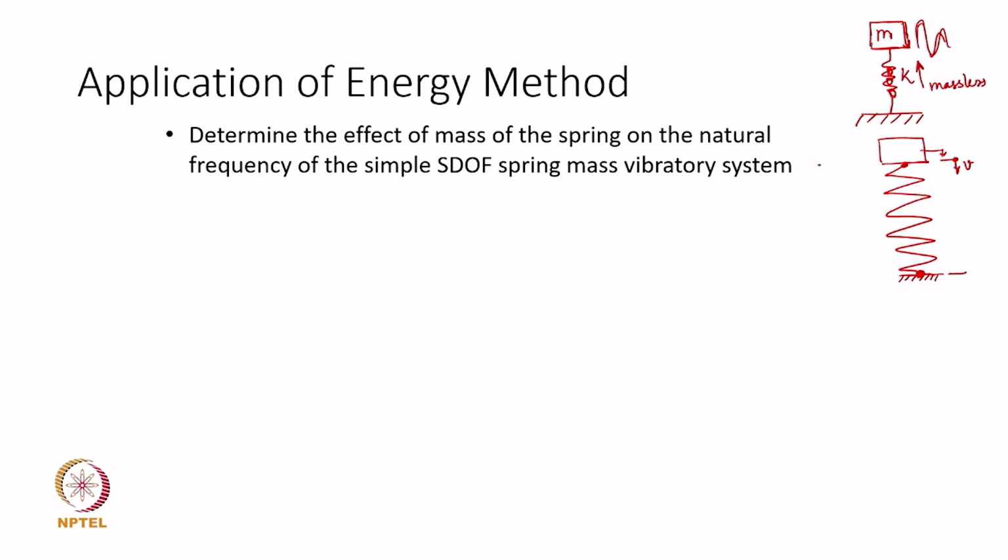Similarly, if I show the displacement, then the displacement is going to be maximum at this end of the spring, and it will be 0 here. So, we can assume a linear displacement profile, which means that if the displacement here is 1 unit, it will keep on gradually reducing. Each of these individual spring elements will have a displacement linearly related to its position from the fixed point.